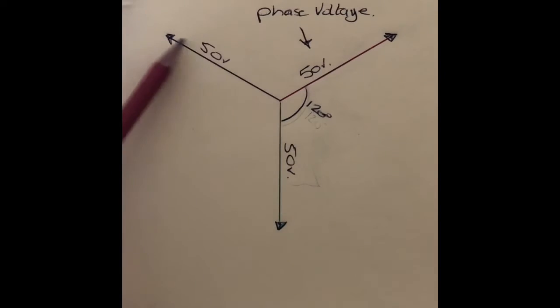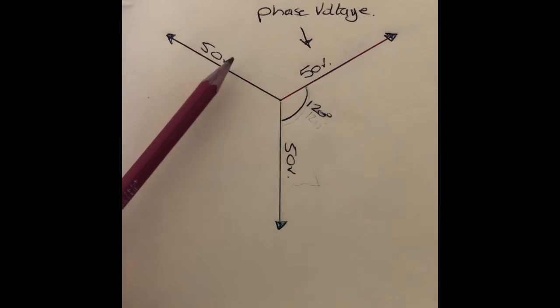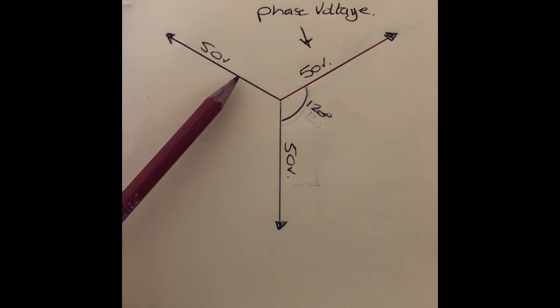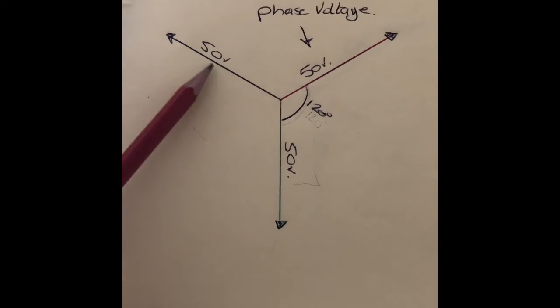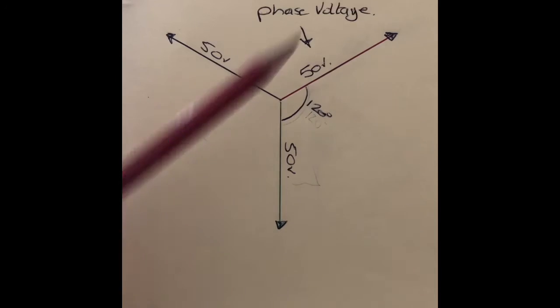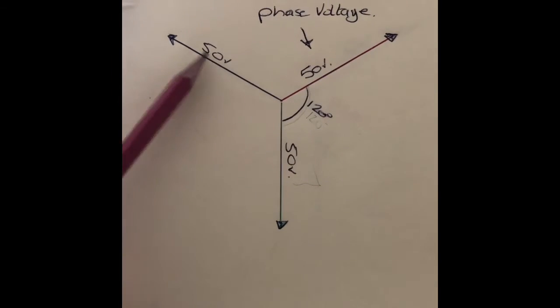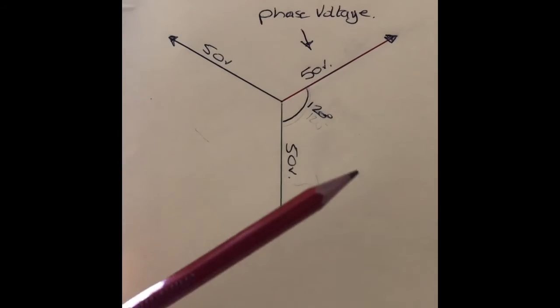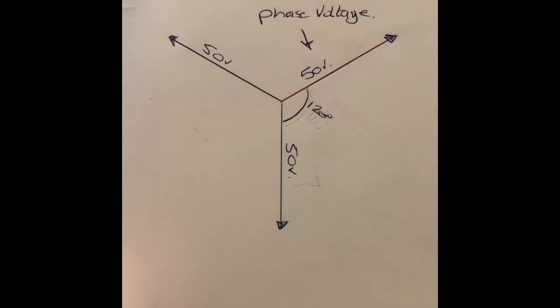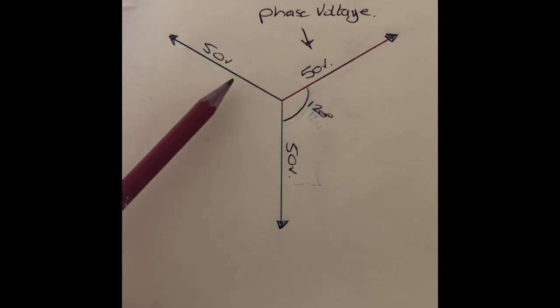If, however, these are unbalanced, so in this phase the system is only allowing it to use half of the voltage, we still need to produce the total voltage in phase 1 and phase 2. However, phase 3 isn't using all of it. Because we're having to produce it, in this phase we would now have a loss. The loss would just go directly down the neutral path and be dispersed in ground. Therefore, we still pay for the full production, but we're choosing to waste whatever's been produced. This is a massive cost to any generation firm. So therefore, they implement a charge.